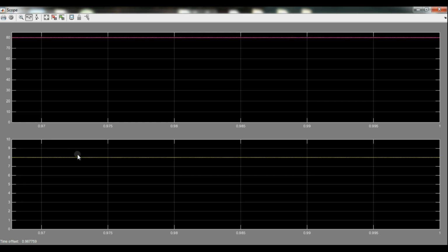Designing this in such a way, we need a capacitor of 10 microfarad, which is costly. So you can bargain between the limits. Here we reduce it very small. If the customer accepts from 7.5 to 8.5, then we can reduce the value of the inductor. If he is satisfied with some ripple, we can reduce the value of capacitance so that the cost can be reduced.